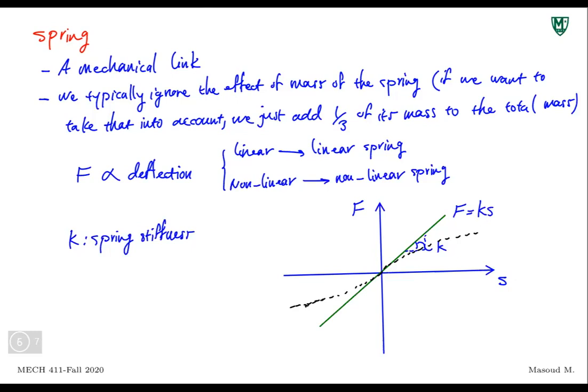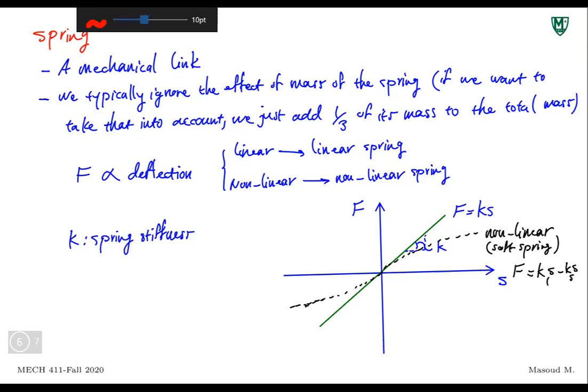This is nonlinear, and it's a soft spring. If I want to write the equation for this, this would be F is equal to K1S minus K2S cubed, so that shows the relationship between the force and the deflection.